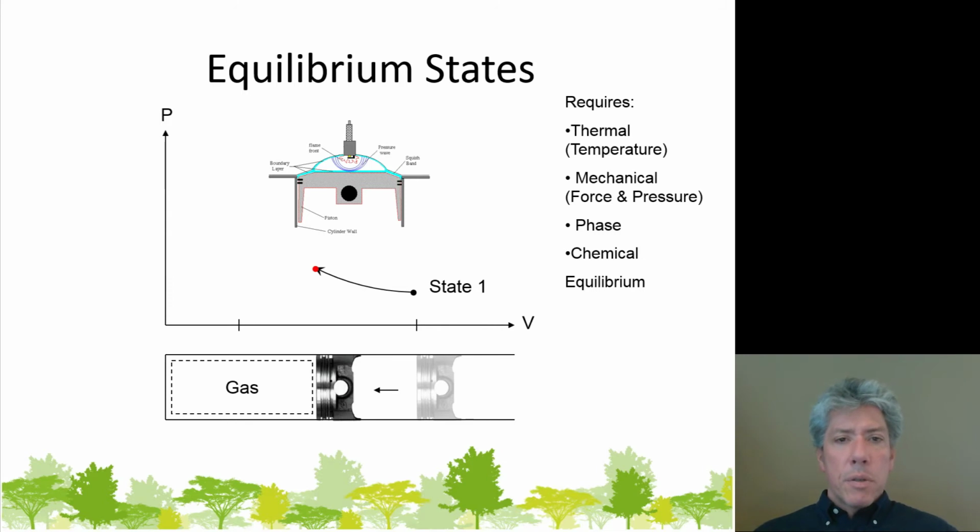Now, what about in a real engine? What really happens above the piston cylinder device? Well, look up at the schematic I've got. It's a cross section with a spark plug in it at the top, and you see the piston is at top dead center. It's as high in the cylinder as it's going to go, so the system is really compressed here. And imagine what happens once the vapor fuel mixture and air is ignited by the spark plug. Well, I don't know if you know this, but in a real engine, you actually don't want all of the fuel to burn at exactly the same time. If that happens, you actually have something in your engine called detonation. And detonation is kind of like taking a hammer and just beating the top of the piston every time the piston comes back up.